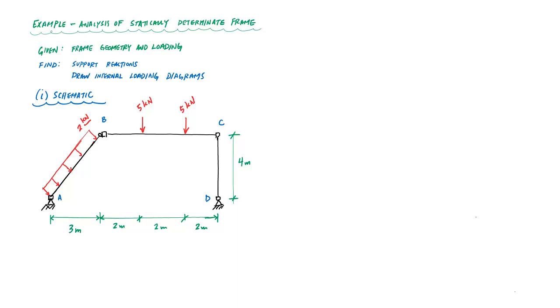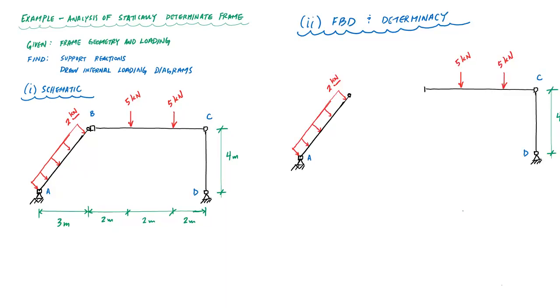And so if there's no closed loops on the structural frame, one of the things I can do is just separate at any of the pins or hinges and count equations and unknowns. And so here is my schematic for the determinacy. So this is what my system looks like if I separate at the pin at B, and here I would have reactions, if you will. So I'll call this like BY and BX that basically connect the hinge or the pin together. There's no moment resistance at a pin because it's free to rotate, and so here equal and opposite.